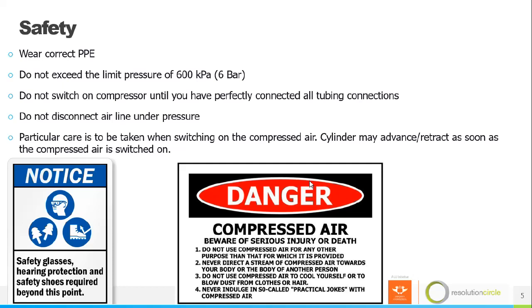And since we know that pneumatics produces excessive noise, we must put on our earplugs. According to safety, if your working environment produces noise that is above 83 decibels, that environment is no longer safe for your ears, so you must use earplugs.